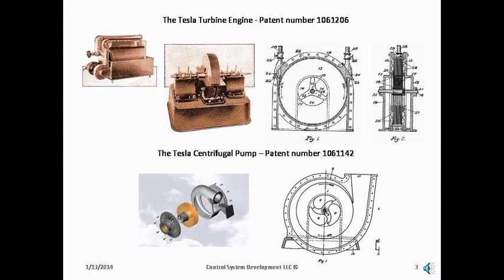The top row of the slide demonstrates a Tesla turbine with 20 9 3/4 inch discs producing 110 horsepower at its maximum efficiency, with the capability of generating 2 to 3 times as much horsepower. The bottom row is an example of a Tesla pump currently being produced and sold. Engines and pumps operate by virtue of viscous adhesion to the disc surfaces.